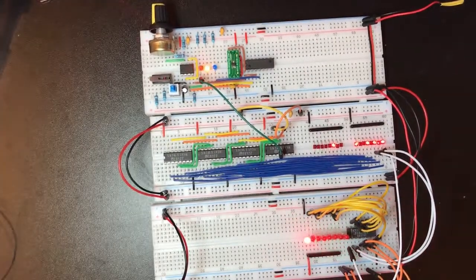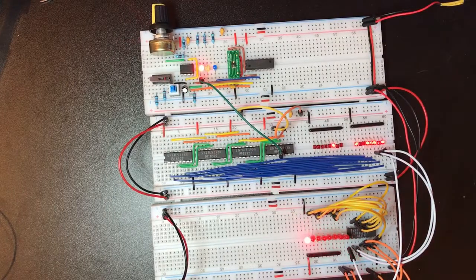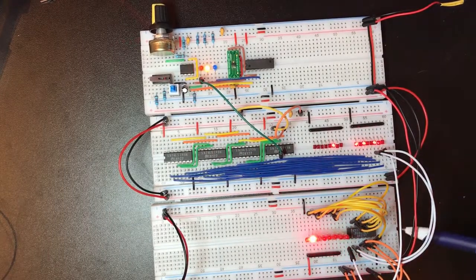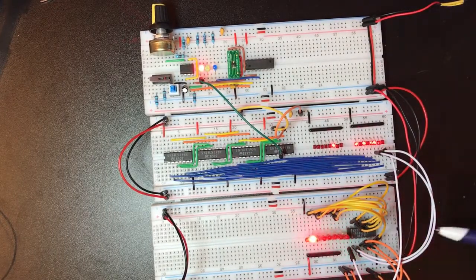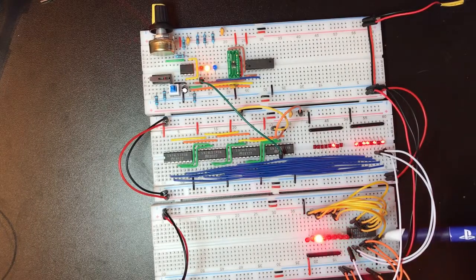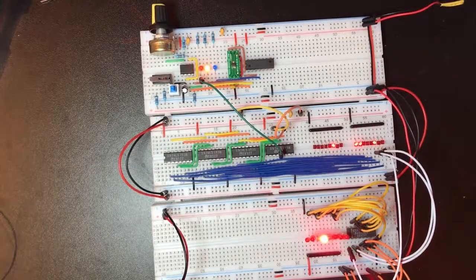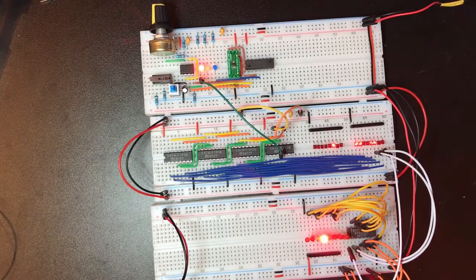Okay, so that's the initial problem solved, but this is really quite elegant and quite simple. This is quite a simple and actually fairly cheap chip, so drop one of these in, we can now select any one of 8 registers from 3 lines. So simple, in fact, I think it would actually be pretty nice to make more use of these.